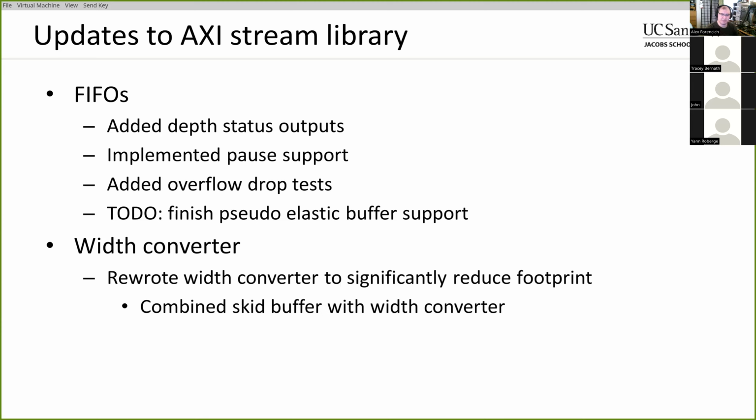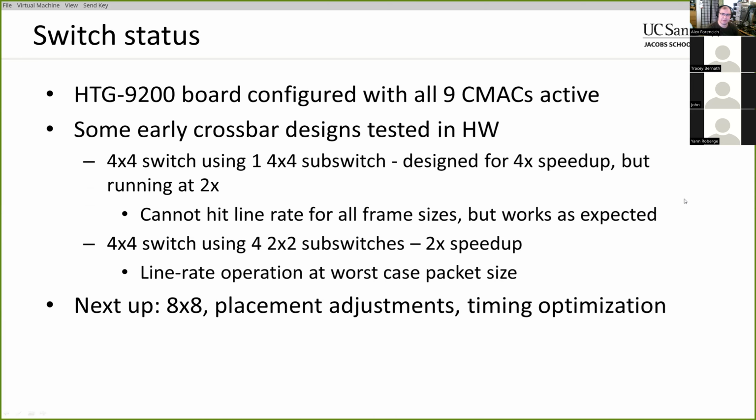I've also been thinking about merging the width converter logic into the FIFOs as well, because if that's merged into the FIFO, then you don't necessarily need another set of pipeline registers, or output registers, so you could potentially save a few more logic resources. I haven't done that yet, but I'm thinking about potentially doing that.